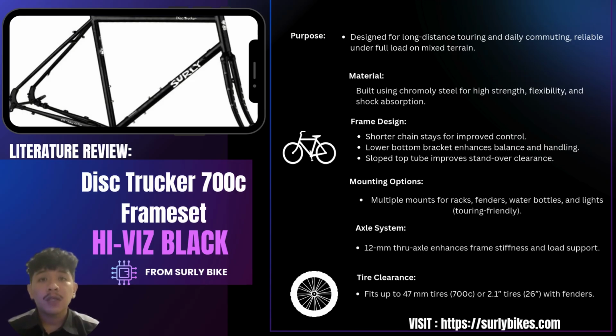So, literature review. I will explain about the Disc Trucker 700C frame set, high-gloss black. The purpose of this frame is designed for long-distance touring and daily commuting, reliable under full load on mixed terrain. The material used is chromoly steel for high strength, flexibility, and shock absorption. The frame design has shorter chain stays for improved control, a lower bottom bracket for enhanced balance and handling, and a sloping top tube to improve standover clearance.